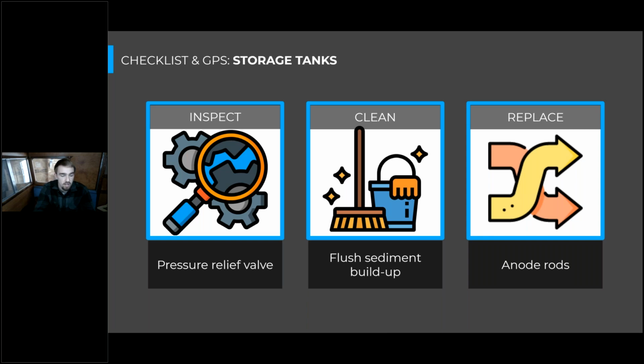So the general theme here though is it's still a heat pump system. So it operates very similarly, but you want to check in with the manufacturer of that equipment to make sure that there aren't any additional unique requirements for that. And for VRF, they're still heat pumps. They change speed, and sometimes they have additional components to reroute refrigerant that need to be looked at specifically. But in general, I think the maintenance of the coils and things like that are going to be really similar.